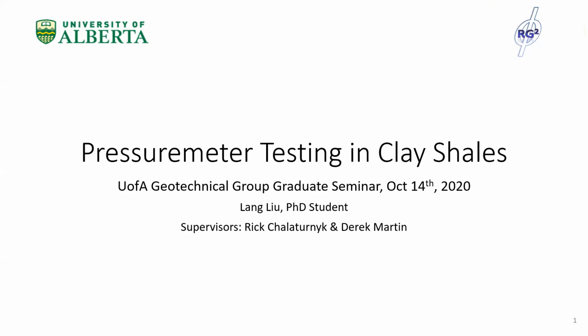It is a type of in-situ testing method that has been used in geotechnical engineering since 1960. And there has been lots of research work done, mainly in the last century, regarding the improvement of the testing methods as well as interpretation theories. However, most pressuremeter tests are in shallow and soft deposits, such as clay and sand. And in this presentation, I will cover the work we did in the clay shale formations, which is at a much deeper level.